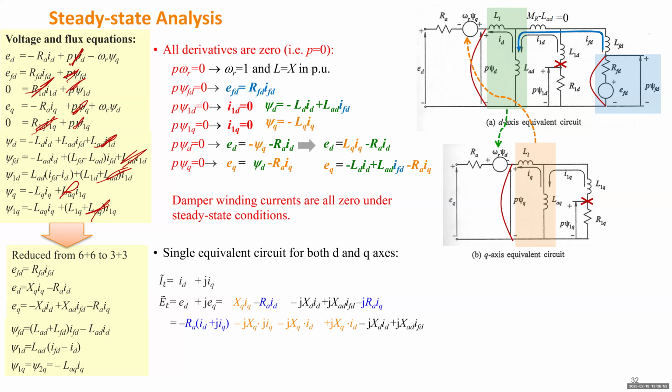All right. So now we can merge the first two orange items into something like one reactance multiplied by the current phasor. But the last three items have something in common: they are all purely imaginary, which means they are all pointing in the same direction. So we simply define the summation of the last three items as some internal voltage.